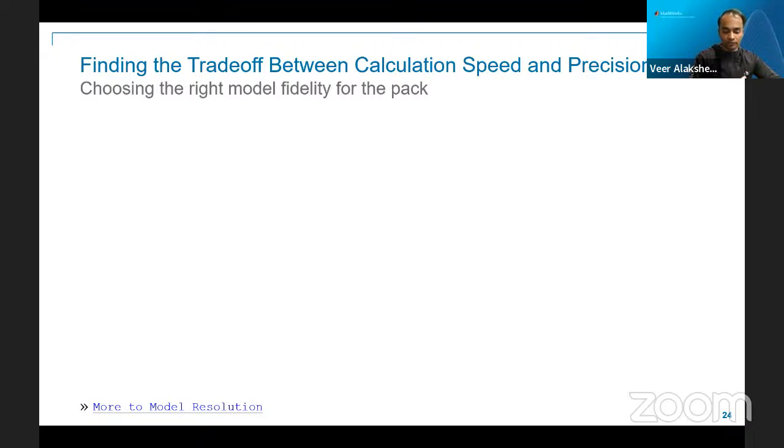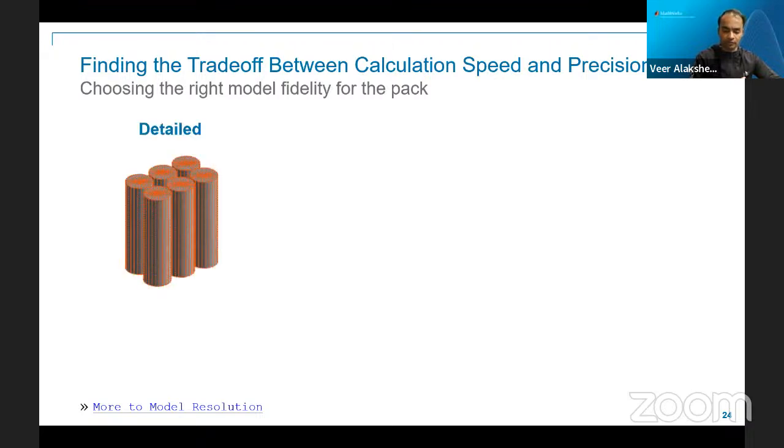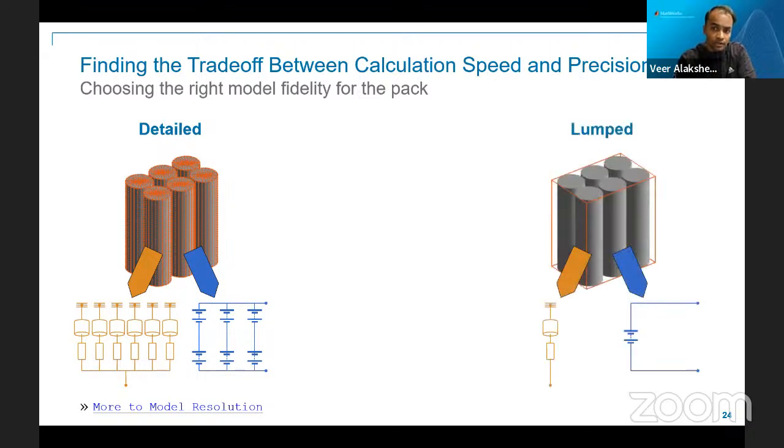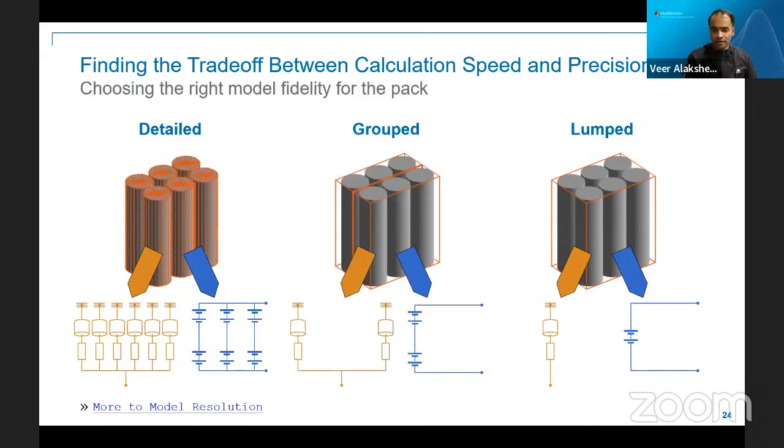Now, getting into detail of that, there could be multiple applications. Someone from your battery department wants to build a BMS system, and their whole focus is on each of the cells. So you can have the options for a detailed modeling of your battery pack, where you can see the thermal equivalent and electrical equivalent. Or your aim is just to have a battery pack system where you don't care a lot about each of the cells. You just want to test this battery, measure the voltage, measure the temperature as a lump, and club it to maybe a powertrain model, and just measure the state of charge.